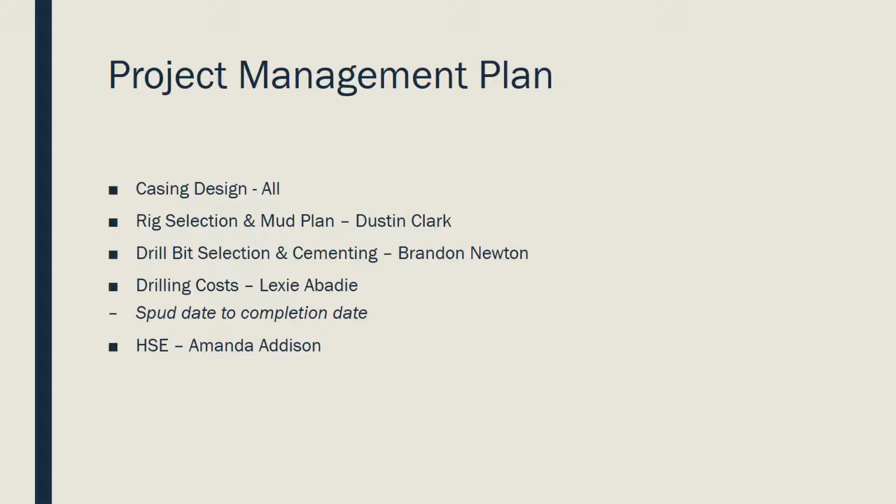Bit selection is critical in minimizing costs and optimizing drilling performance. To select the best bit, we will analyze the pros and cons of different types of drill bits and how each one performs in different types of formations. We will then use the data we have on the formations the well will be drilled through to pick a drill bit that will give us the performance and longevity that we need to be as efficient as possible.